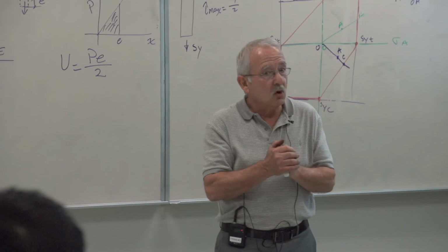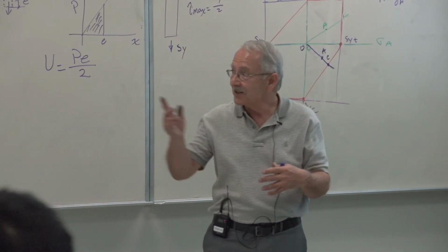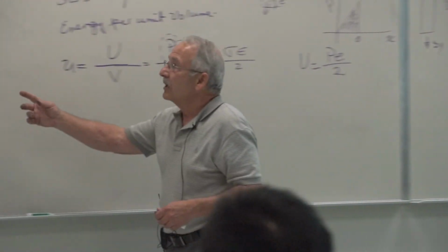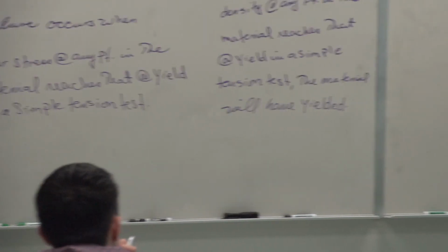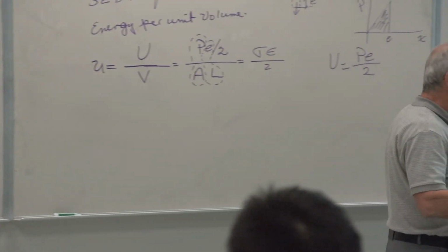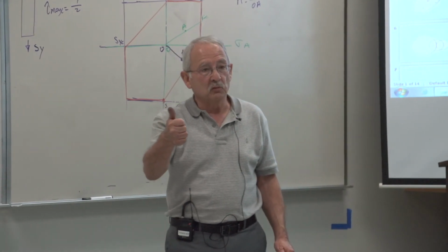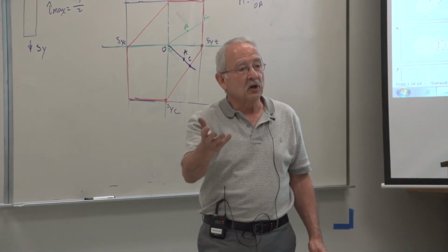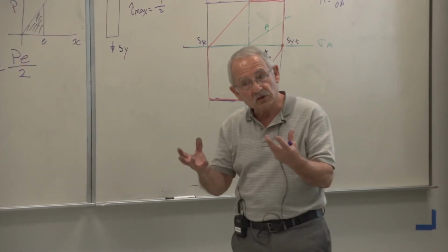Shear stress, as you know, however, changes angles. And that's really the one we're interested in, because that's what causes yielding. So we divide the strain energy into two parts. One, solely due to volume change. The other, solely due to shape change. In other words, the cube doesn't remain a cube.